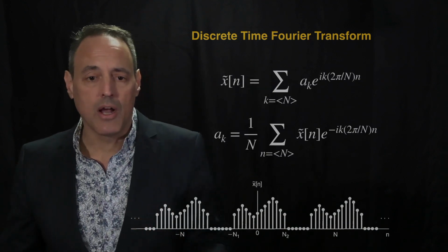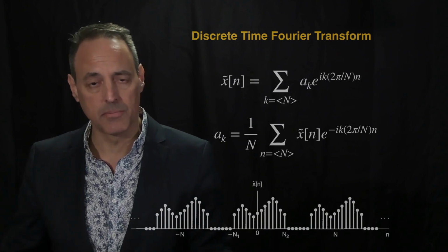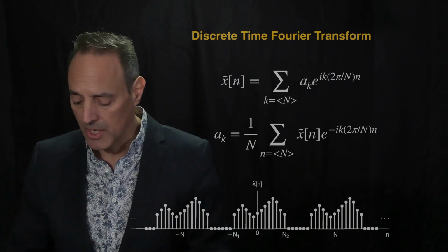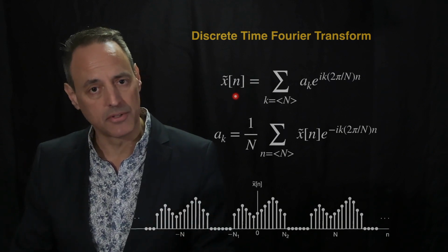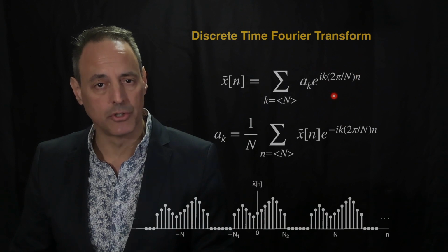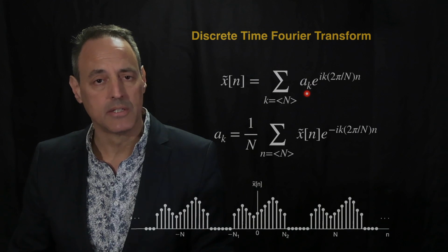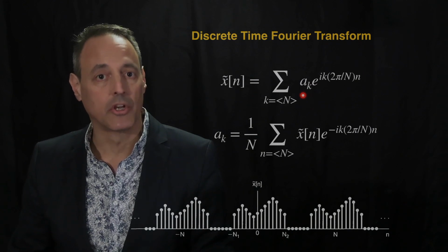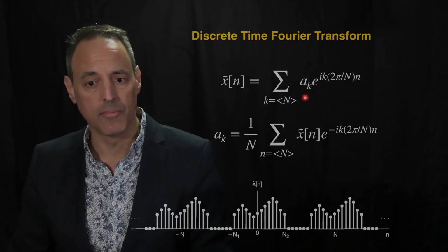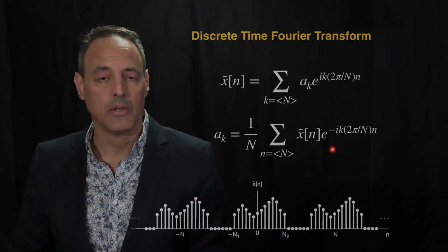So let's talk about how to compute the coefficients in this representation, because actually that's where the work is. We have this approximation to the signal. Here it is. And so you have the Fourier modes you're going to use, and then you just have to say for a given specific signal, well, how do I compute the coefficients of each of these Fourier modes, the a of k? And of course, we've already done this with the discrete Fourier transform.